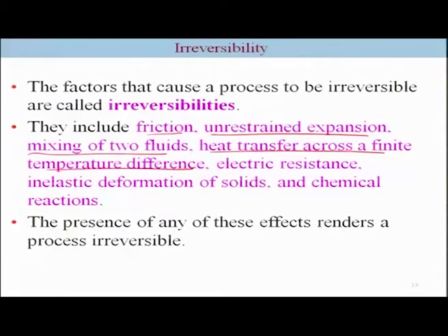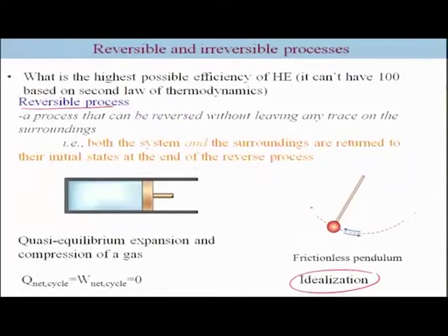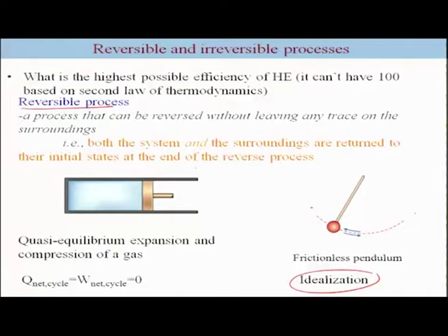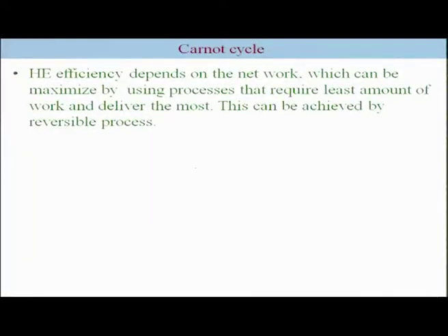Besides this, the one we have talked about is basically the totally reversible process. In addition, we also consider when the system is internally reversible. In such a case, we assume that the system can be brought to the original state, however the surroundings may contain all the irreversibilities. So, in those kinds of cases we call it internally reversible, where from the system to the surroundings there may be a finite temperature difference, but within the system everything is reversible. Those cases, particularly internally reversible, are the ones we are going to consider most of the time when we discuss problems.